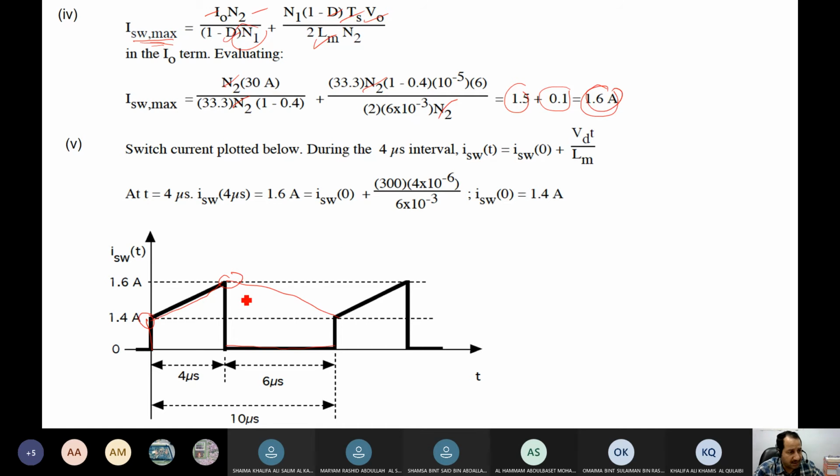I have it. Okay. So this is how I sketch it. It's not only sketching the waveform itself. No, you need to specify the current here, the T on. It's easy to specify, by the way. You know T on equal DTS. You already have D, you have TS, and T off is 1 minus D times TS. Also, you have them. So just put the values. TS is the total, which is 1 over Fs.